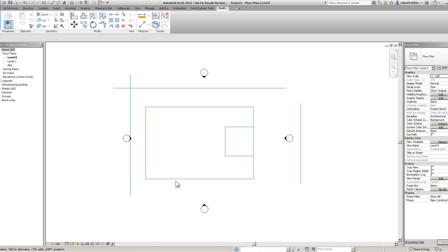Now, what we're going to do, we're going to have a look at our different trim commands. They're up here. I've stayed on the modify command up here just so that I can do it quite regularly. Now, I'm going to hit this one first. This is a tool we use absolutely loads in Revit. It's basically trim extend to corner. It works very similar to the fillet or chamfer with a 0 radius or 0 distance in AutoCAD.